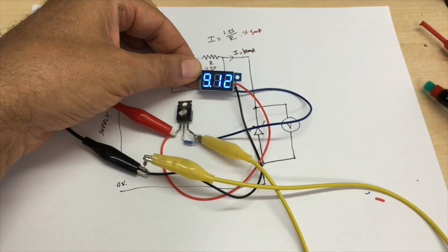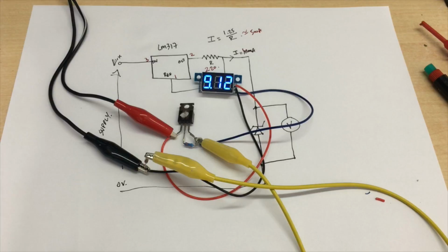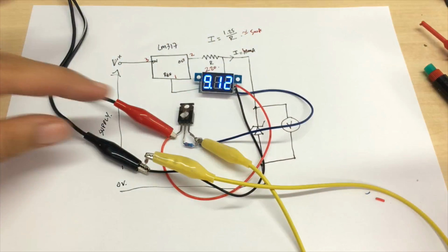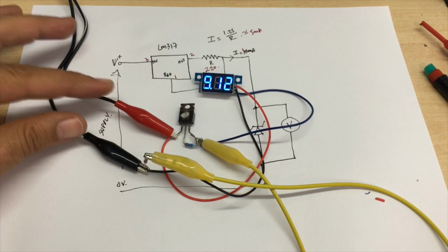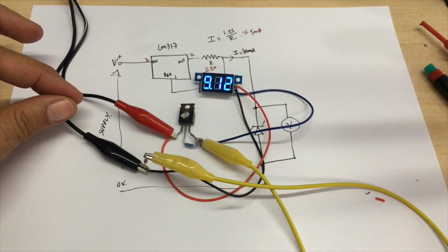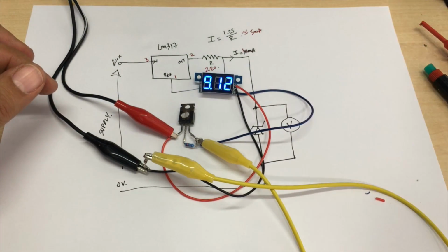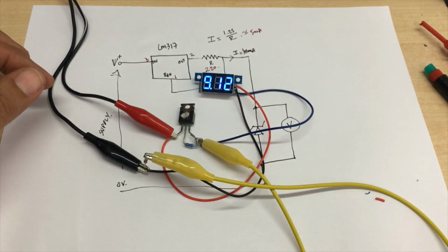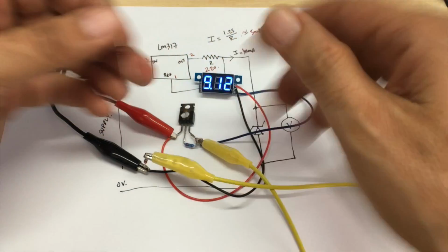Well, there are two ways of doing this. One of them would be to actually use the positive and negative supply coming from the power supply. So I could have a situation where I actually plug in a variable power supply or a power supply. Bear in mind that I don't need to vary the voltage anymore. I can set it at 24 volts, and I can then measure any Zener I put on here that is less than 24 volts. Let's see, this one, I have no idea what this is.